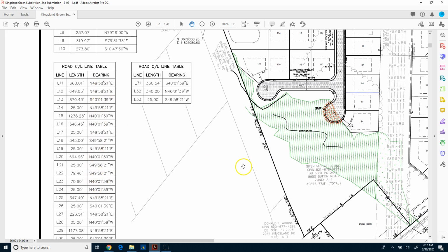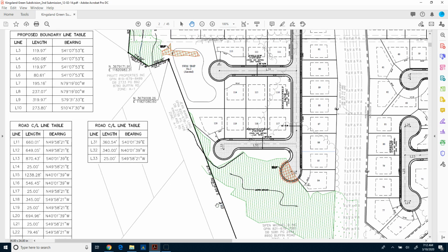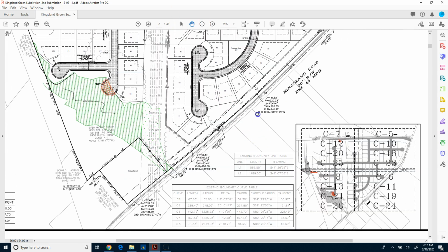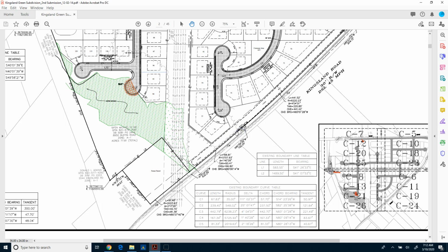Now it's a time-consuming process, which is why getting the CAD file makes things a little bit easier. But if all we had was the PDF, we could do some data prep and rebuild this. Now we would need the coordinates of these locations as well as the road profile, which are on some future sheets. So we'd be able to use this along with a typical cross-section to rebuild this road network using Business Center. So it'd be very easy to take this data and build a model of it using just this PDF. So I'm not digitizing, but I'm actually recreating that information in that line work.